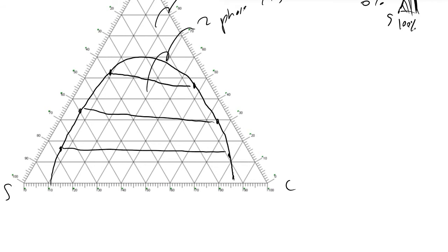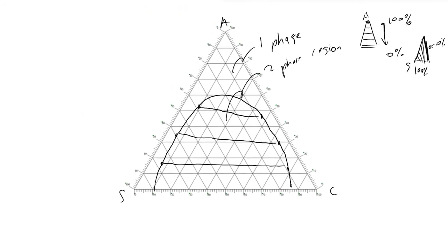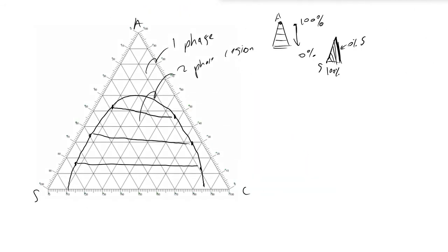And if I could draw better, these would be linear, but you get the idea. And so I will label these things I just drew as tie lines so people can follow. And we will proceed in how do we actually find the number of trays that we want or are needed for a particular system that we are evaluating graphically.